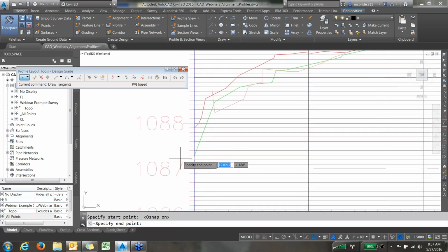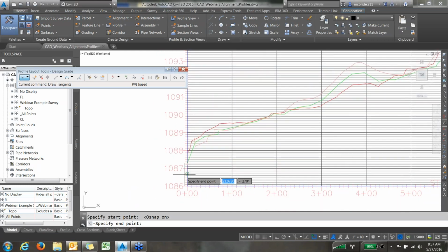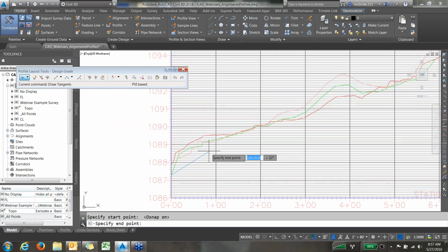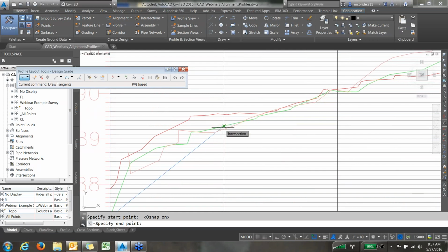And for this particular waterway, I've calculated that it needs to be roughly 1.2 foot deep. Now, this part here is kind of where you have to do some, call it guesstimation. I did a pre-design. I think it's going to be 1.2 feet. It may end up being 1.4, 1.8, whatever it might be. It might be shallower. But that 1.2 is really going to help me start out where I draw this first profile grade line. And so what I want to do is look at each station, say every 100 foot or so, and take the low bank and go 1.2 feet below that.